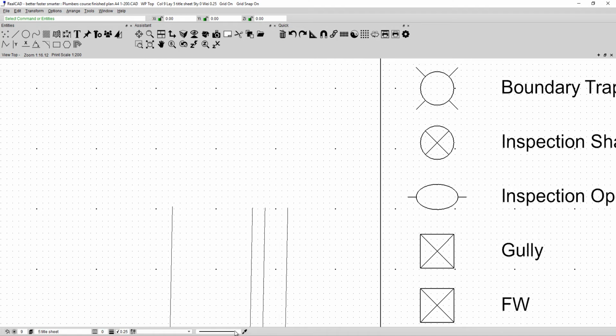which happens to be, as you can see here, black. If I then go up to my upper left and I choose the line tools, and I then choose the very first one, this is the one that you will use 90% of the time when you're drawing, insert a line. I look at the prompt and it says select the start of the line. Now these little dots, if I click, even if I'm not near a dot, it will jump to a dot. And as I move, you can see that I'm getting 100mm increments in the length of the line that I'm drawing.